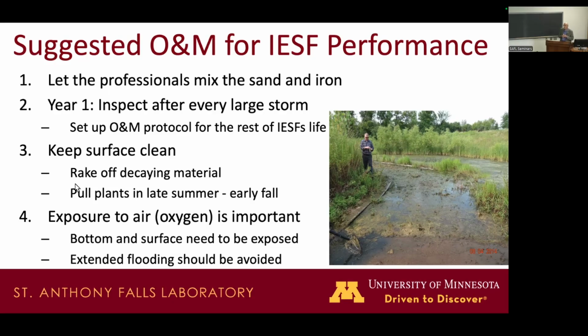If it's flooded for a week, that's not a good idea, because your phosphate will start to come off of your iron. Your ferric iron, iron plus 3, becomes ferrous iron when you have zero dissolved oxygen. You slowly move to zero dissolved oxygen.